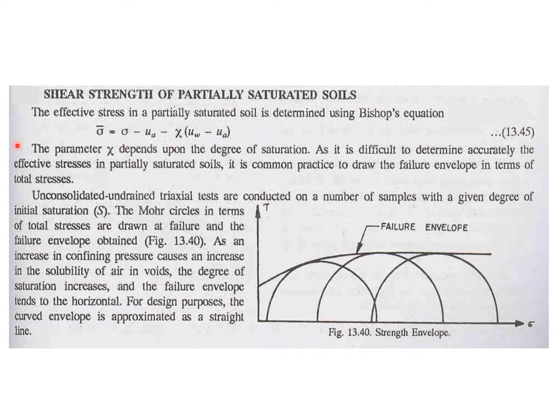The parameter psi depends upon the degree of saturation. As it is difficult to determine accurately the effective stresses in partially saturated soil, it is common practice to draw the failure envelope in terms of total stresses.